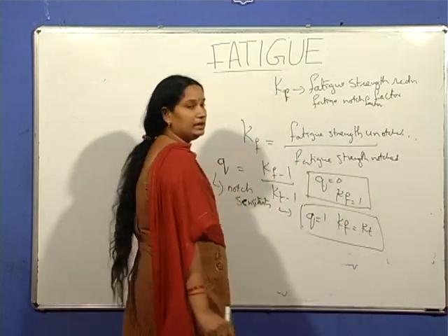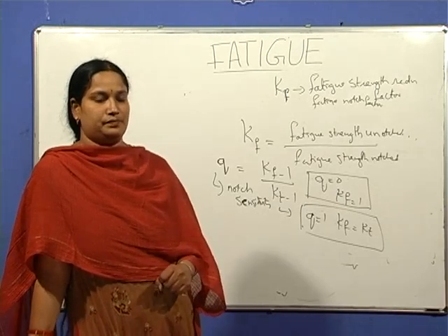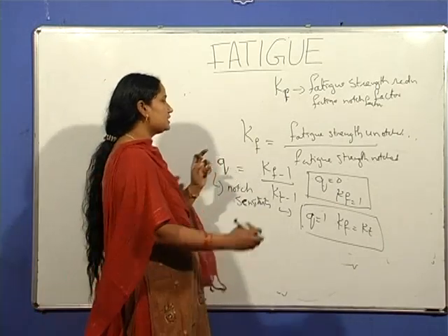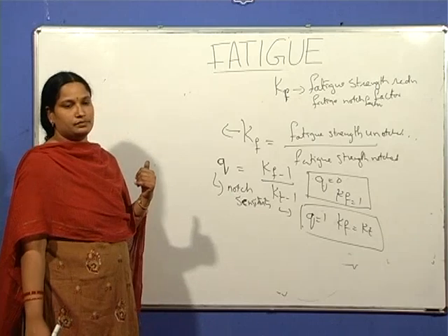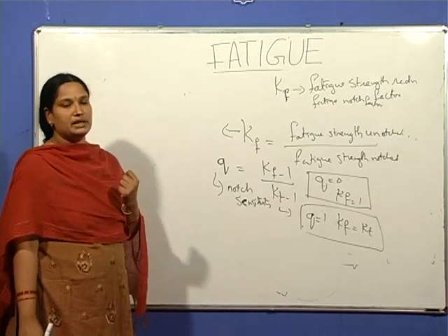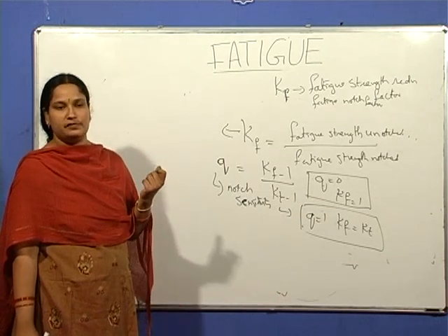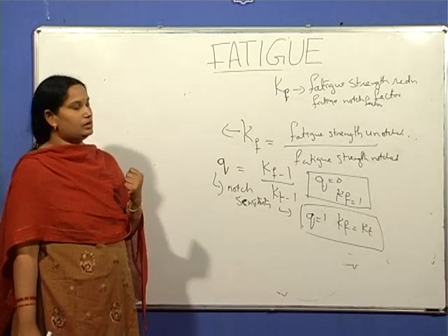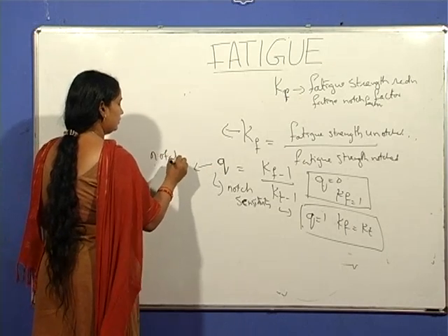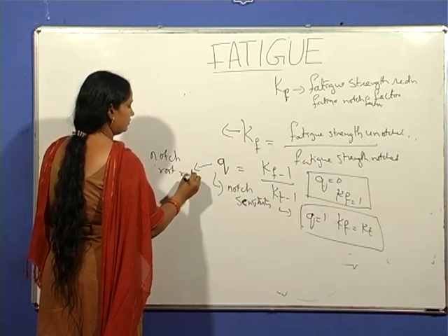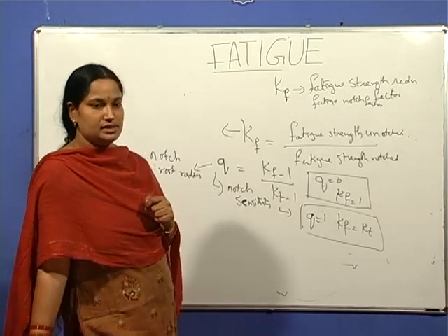So, this q is quite sensitive to the notch radius. Kf depends upon the stress level, as well as the material, the shape of the notch, and the severity of the notch. q is sensitive to the notch root radius.